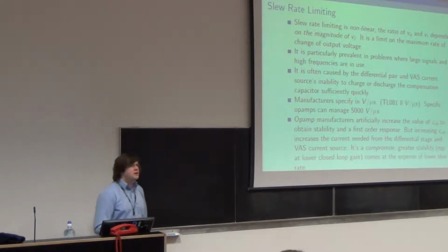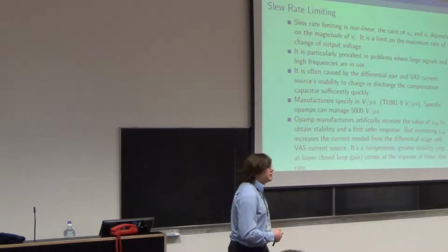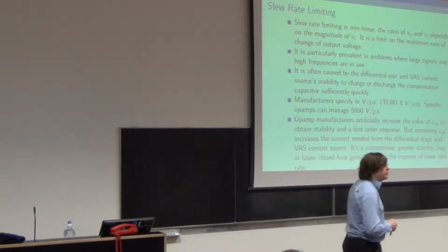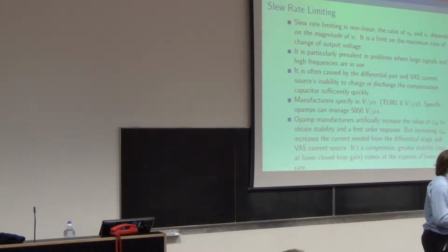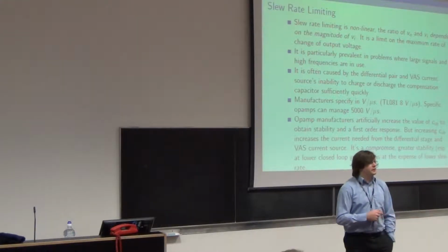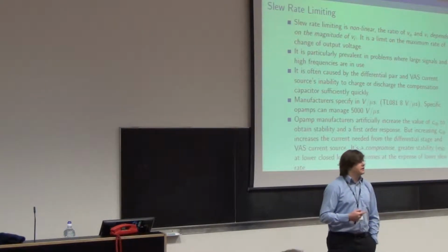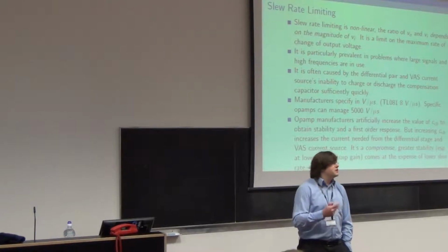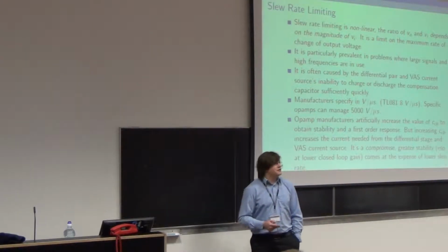So if you were testing an audio amplifier, for example, and you wanted to see what its slew rate was, that's to say so many volts per microsecond at the output, you wouldn't try and drive it with a kilohertz, because it can probably manage that okay. You try and drive it at 50 kilohertz, and you make sure you're doing it at full power. And then obviously you'll need quite a tasty resistor, it's going to get quite hot. But you will then see you're testing it in such a way as to expose its weakness. If you give it an easy test, there's a good chance it'll be fine.